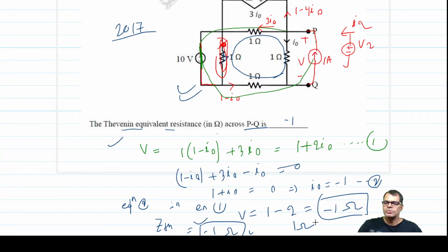To minimize that battery consumption or power consumption in a portable device, we design the negative resistance circuit, so that we can connect it in that oscillator in such a way it can cancel the positive resistance and minimize the loss in the circuit.